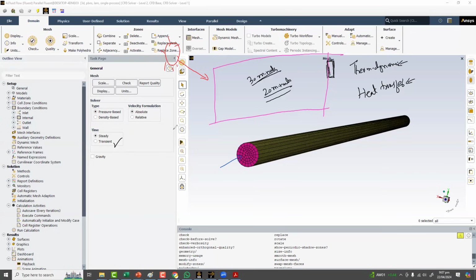Okay, but if I'm solving this case and I'm finding out, okay, in the equilibrium condition with sunlight applied here and air conditioning applied here, what will be the temperature of the room after whatever time it is? So what is the temperature of that room after these energies on the sides of the room? In that case, the steady state is enough. But if I want to find out how much temperature will be on this wall because of the sunlight, how much cooling will be there because of this air conditioner here, and how much time it would take, this is a transient case then.